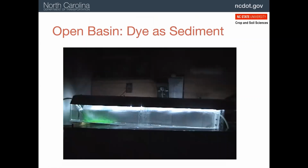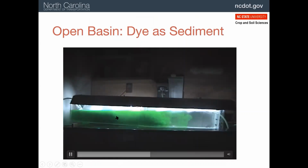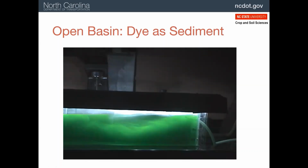To show how porous baffles work, let's look at a laboratory demonstration of an open basin. And the dye you see here is sort of representing your turbid, muddy water. So picture that. And here we go. You can see the flow coming in, a lot of turbulence. I've sped it up so you can see the whole basin has a lot of turbulence. So that's important to think about when we go to the next slide.